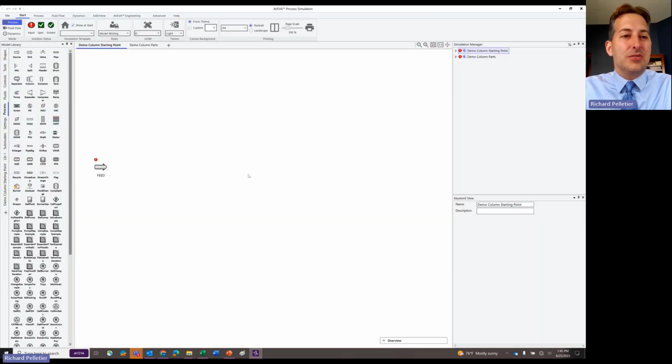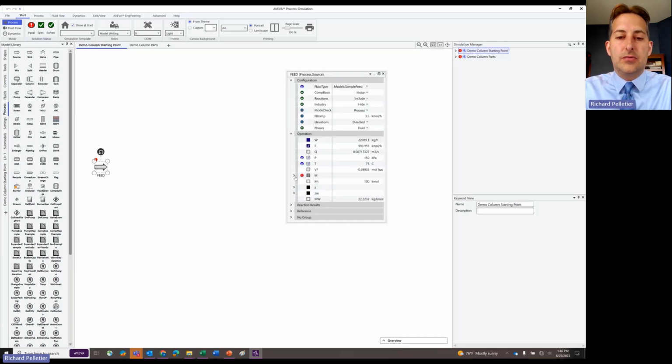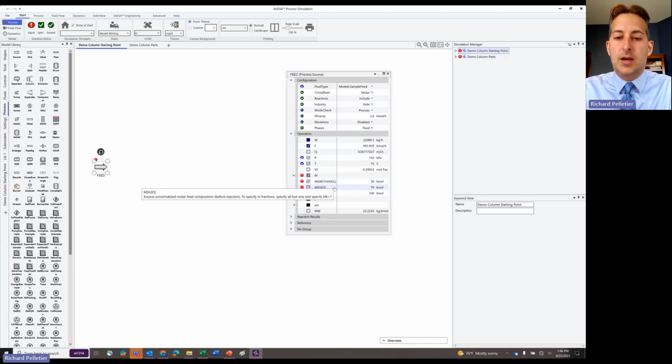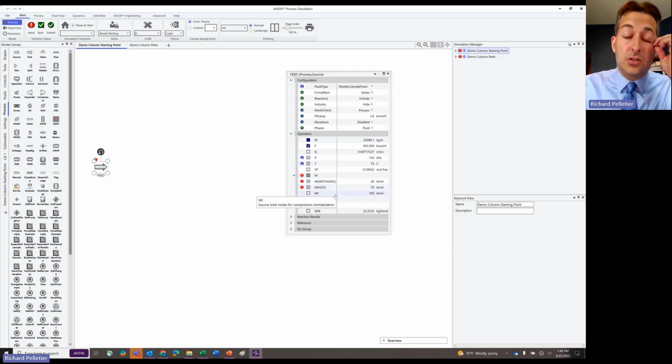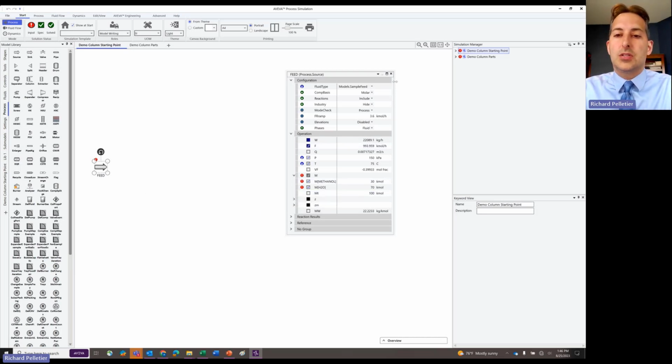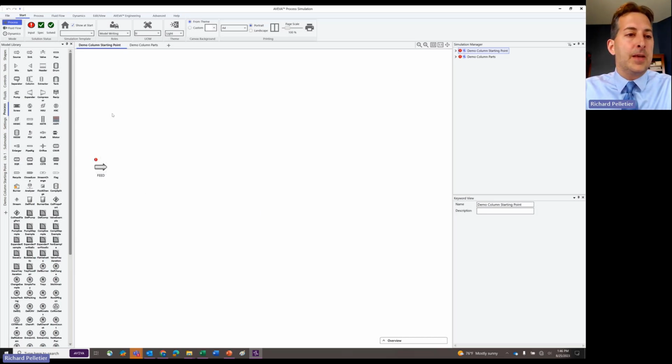All right, we're going to switch over to the software, and we're going to demo building out a column from scratch. And as I do this, I'm going to talk to you about the concerns related to the workflow process and the typical things you're going to want to do when working with a column. So again, first thing, make sure I'm square and solved. Make sure my feed is ready to go. So in this file, we have a methanol water column that we're going to be trying to separate. This is not a very complex simulation. This is going to be pretty straightforward. All right, so this is just two components, and we're just going to separate them out.